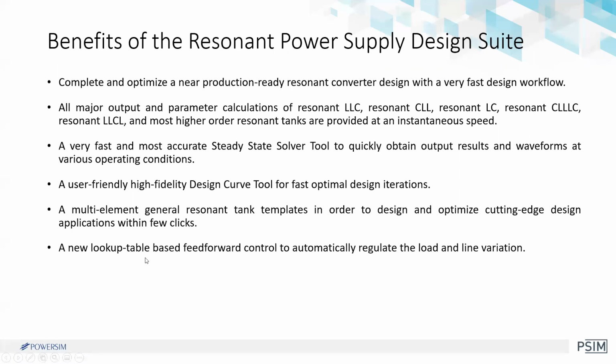And the lookup table helps us quickly get the frequency, because in a DC-DC converter, we know the formula for a buck converter: from 12 to 6, your duty cycle will be 0.5. But for a resonant converter, an LLC converter, or any resonant converter, it's very difficult for anybody to say what your precise frequency should be at a particular input to get a particular output, right?